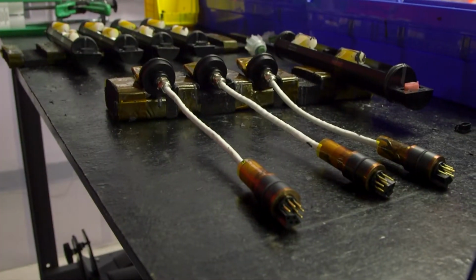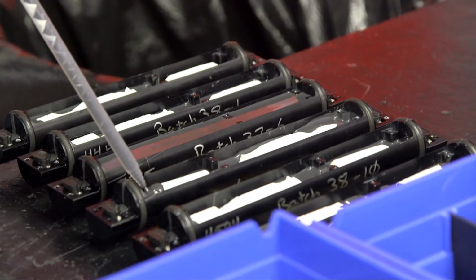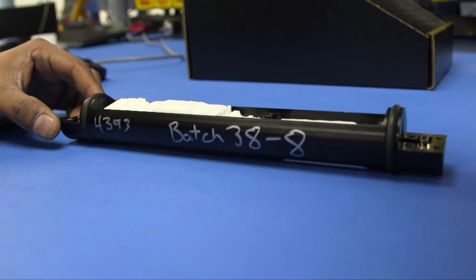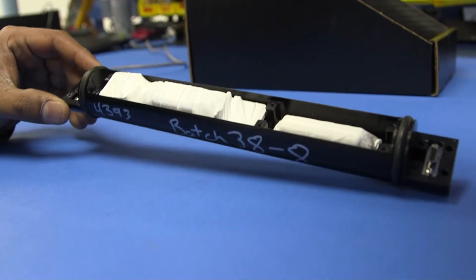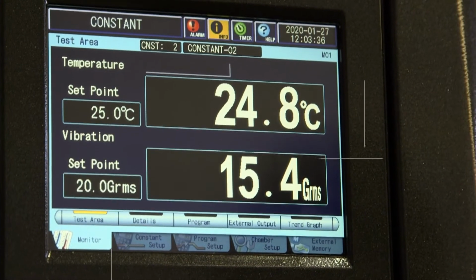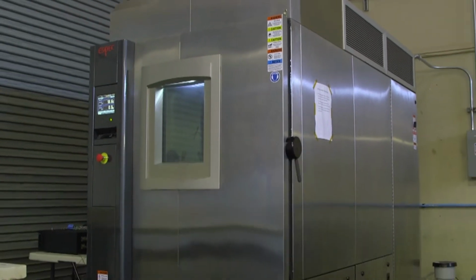The fully processed electronics boards are now fully encapsulated in a silicone RTV for shock and vibration isolation. The assembled board that's been potted and epoxied is wrapped and inserted into a chassis. Assembled chassis are then rigorously tested in our HALT/HASS chamber, simulating extremes of temperature and vibration.